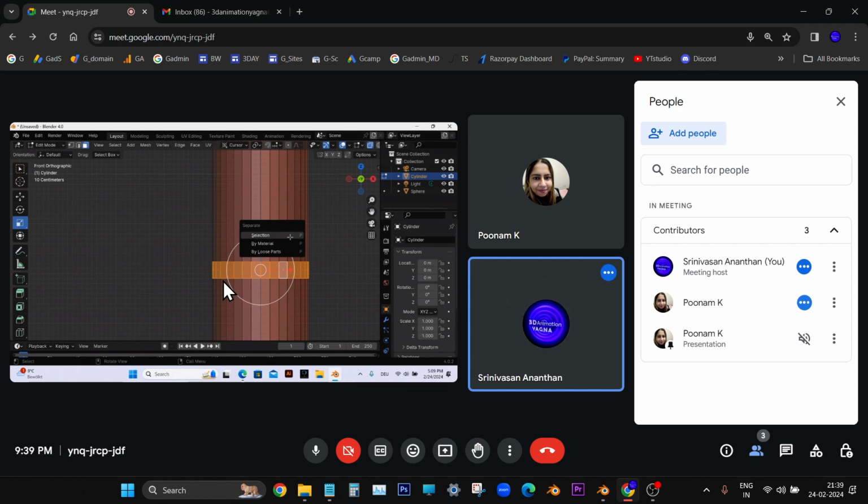Selection. Now you see, you don't click anywhere. You see some orange color is being formed. Even in the outliner you can see cylinder something is formed there, on the right. Do you see that Cylinder.001 is there, on the right side in the outliner? It is in orange color selection, which means inactive selection. Yellow color is active selection, orange color is inactive selection.